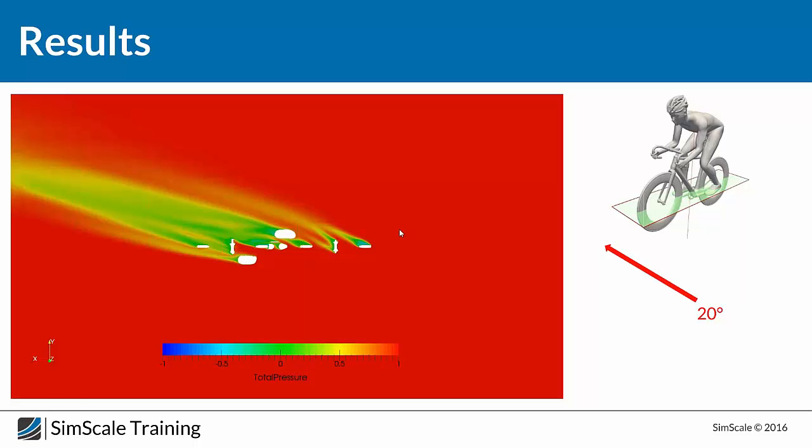Not really. I think you talked about most of the important things. What I really like about all this picture is that it really shows the trade-off you have. For example, if you have the large wheels, on the one hand it's stabilizing the flow as long as you have no yaw angle. But from the moment you have yaw, it can also be a big disadvantage, like the large wheel which is acting in the end like a plate in the flow.